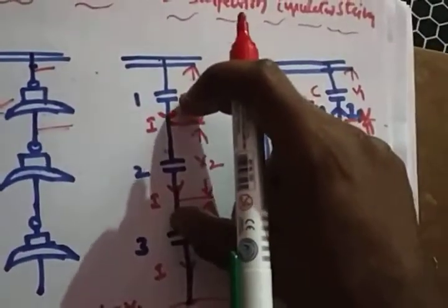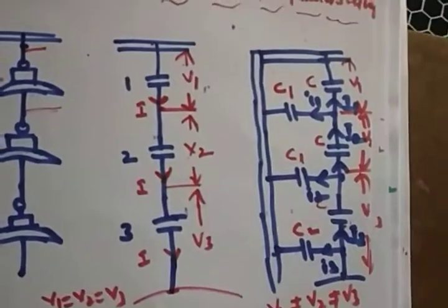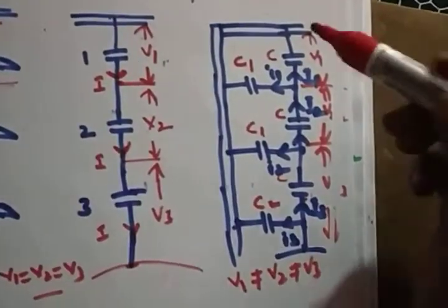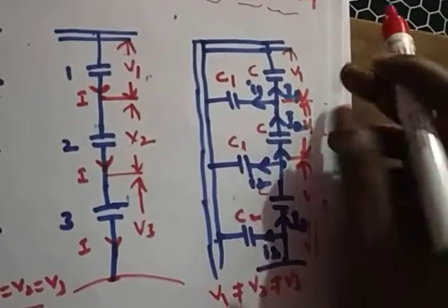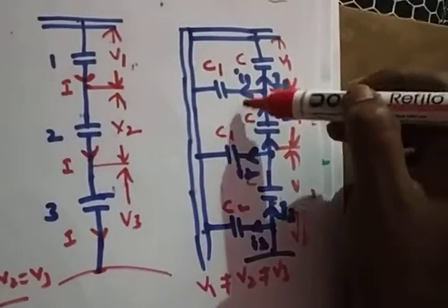If the same current flows through all these capacitances, there is no chance of maximum stress. All the discs are at equal potentials, right? When a shunt capacitance exists between the metal conductor and the supporters, the current will vary.